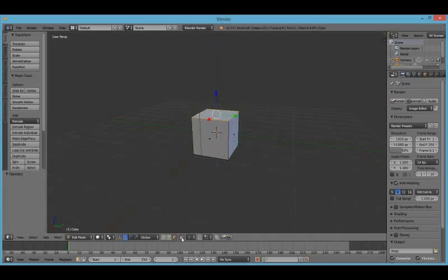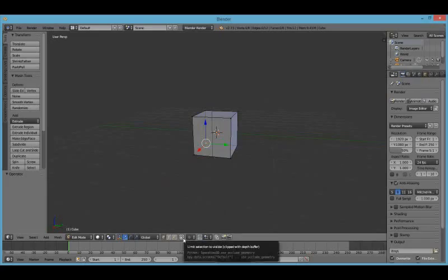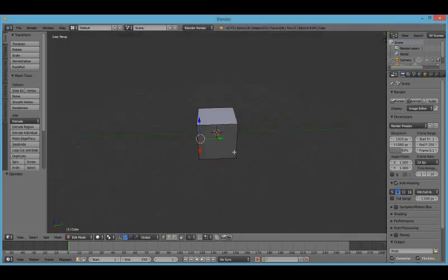Over here just to the right of that, there's a transparency button. It enables transparency on the mesh, in this case the cube, and allows you to edit in behind where you'd normally be able to. We're going to leave it unticked for this tutorial though. Let's add some geometry to our mesh. A little more to play with. There are a few different ways that I want to show you to add geometry to your mesh.